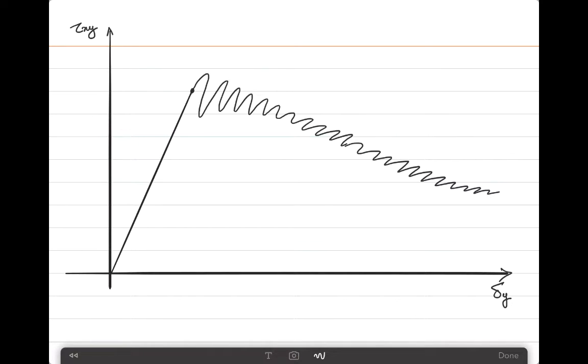Now I can relate this result back to what I already said before about what happens when the crack tip appears and the mesh dependency. Let's say that this is the first model, where the mesh is not sufficiently fine. So what we see is that you have a limit point over here that becomes clearly visible in the analysis.